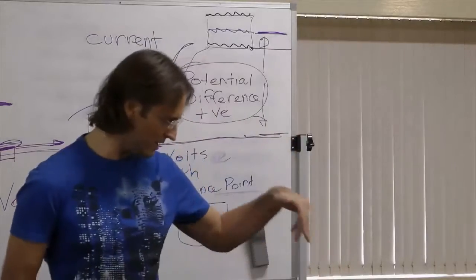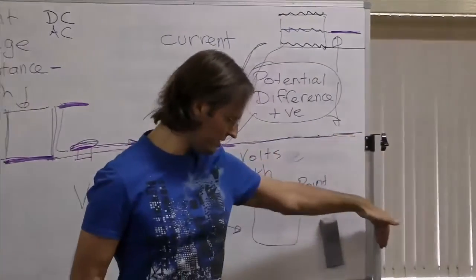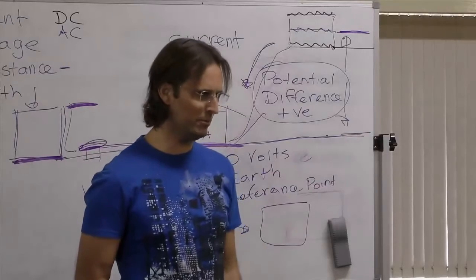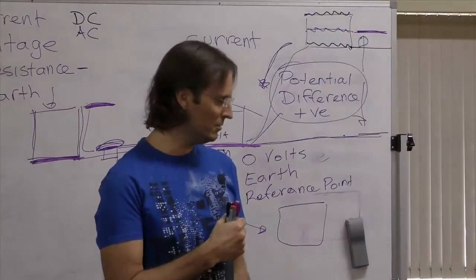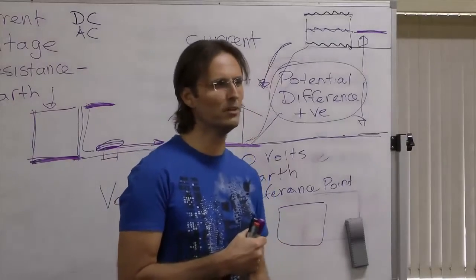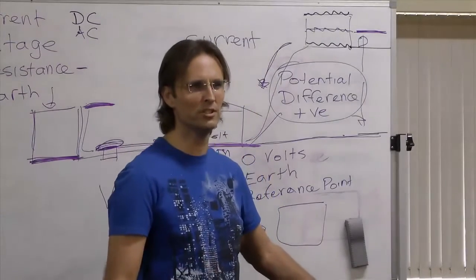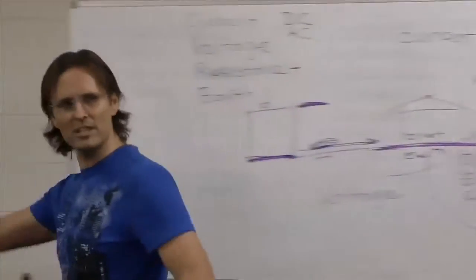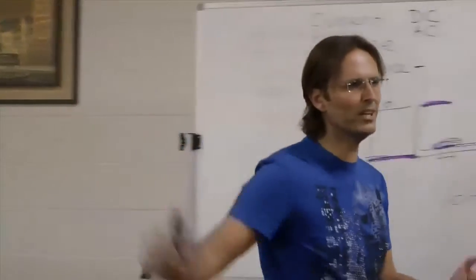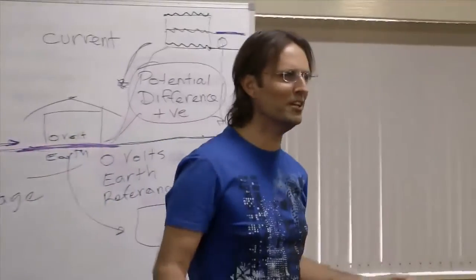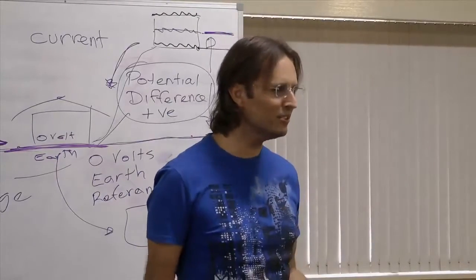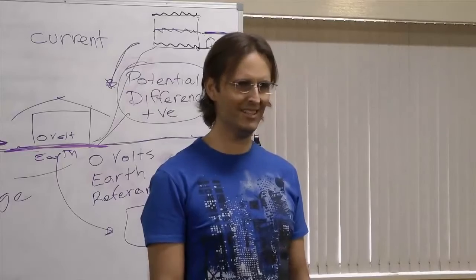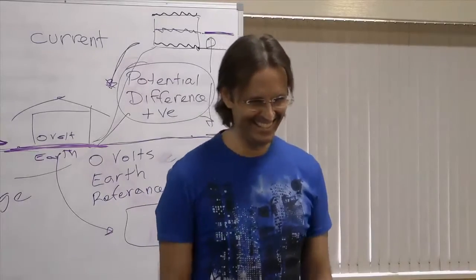So let's say a lightning strike happened here, and you could stand here, and you're still probably going to feel the effects of that strike because of what's happening on the Earth around you with the dissipation of the energy. But if you stood over here, 20 metres away, you'll hear it, see it, might be frightened by it, but it's unlikely to actually hurt you. That's why you keep your feet together when there's a potential lightning strike.